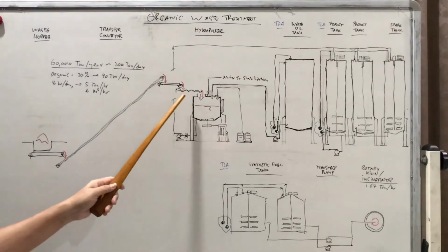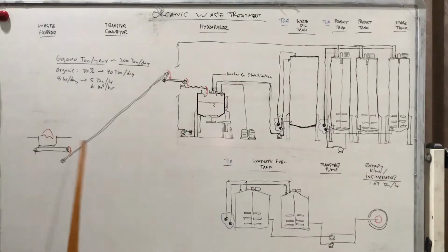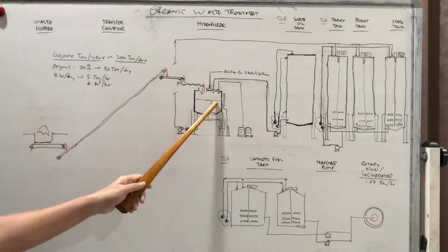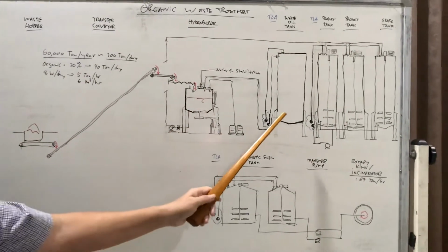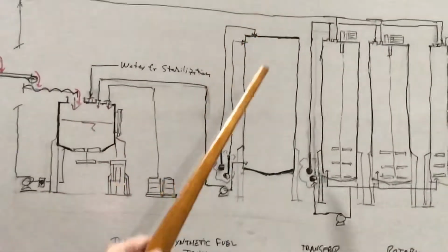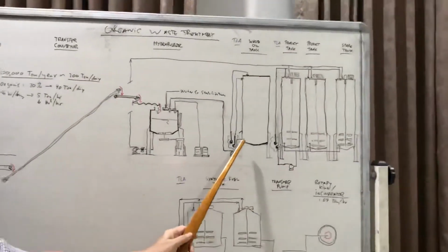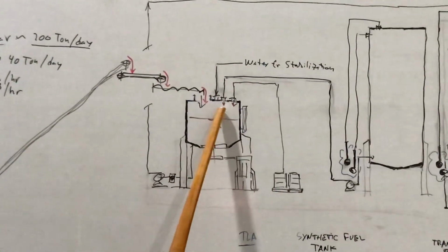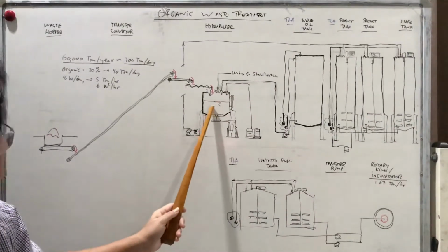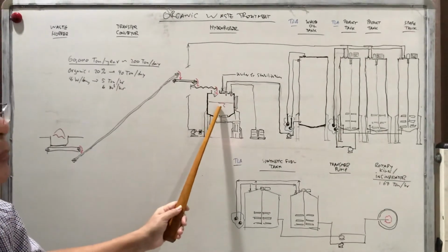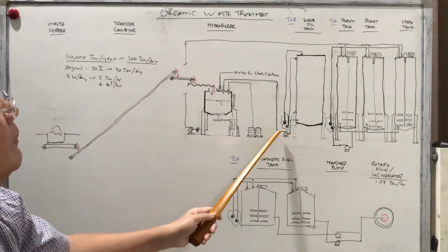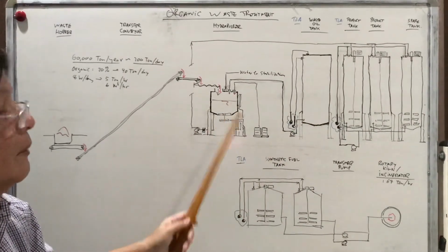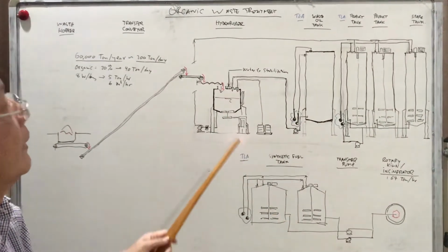Before you put in the solid material, you first put in the waste oil. This is the waste oil tank. We pump from this tank to the hydropulper. The volume of the hydropulper is about 2 cubic meters. So when you pump in the waste oil, it's maybe around 1.5 cubic meters.